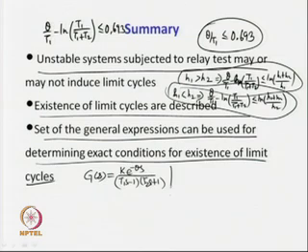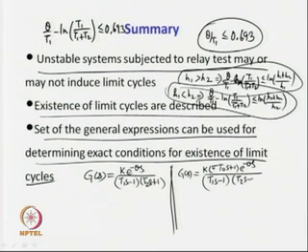Now, what about other types of unstable processes? When the unstable process G(s) has a zero, of the form k (plus or minus T0 s plus 1) e to the power minus theta s upon (T1 s minus 1)(T2 s plus 1), please make use of the condition that lambda 3 is not equal to infinity. Then you will get similar analytical expressions involving lambda 3 in all those expressions.